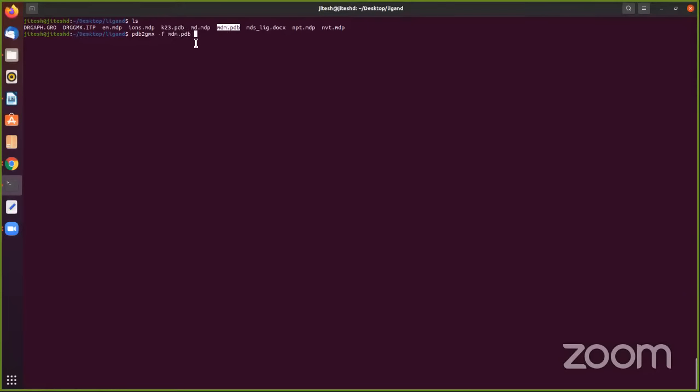Now these are separate currently, but after we convert them into topology and the Gromacs file, we will come back and combine them. Next, it requires the output file. You can give it through the -o option. So on the command line, as you can see, the pattern is followed for every command. It starts with, first of all, gmx. That should be your first word. Within gmx, you give which program you want to use, and then the input and output parameters for the program. So how do you want to save the output file?